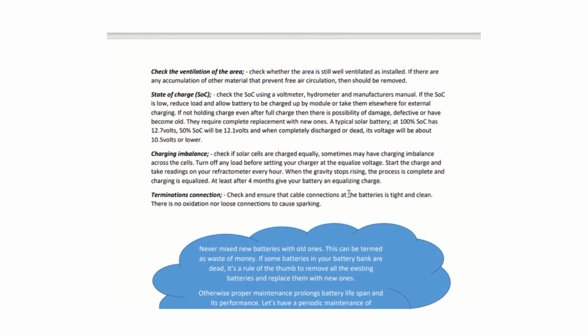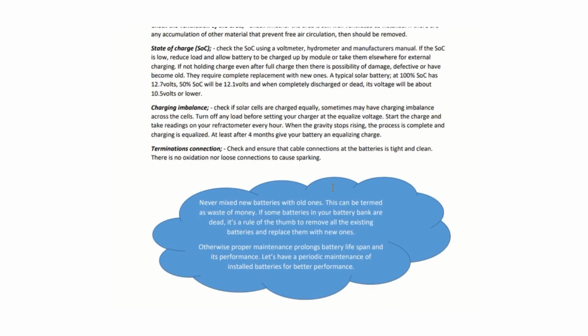Another important thing is charging imbalance. You must check, are the batteries charging in a balanced way? If there is imbalance, then you must see which battery is not charging to the same level as the other batteries, and this one is very, very critical.